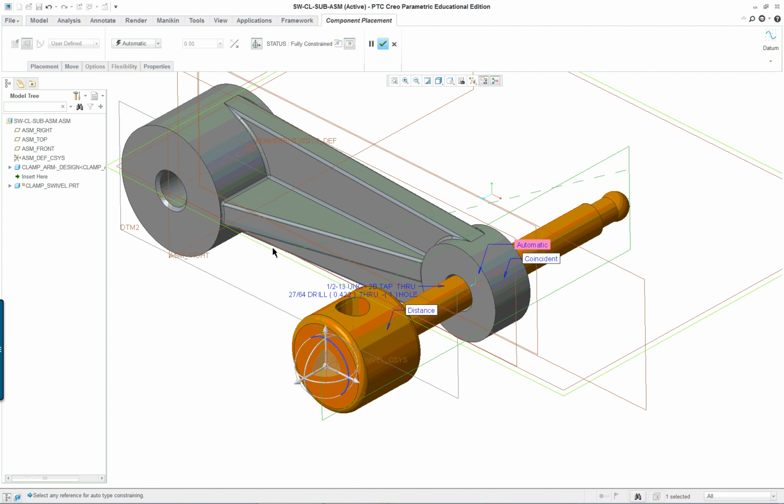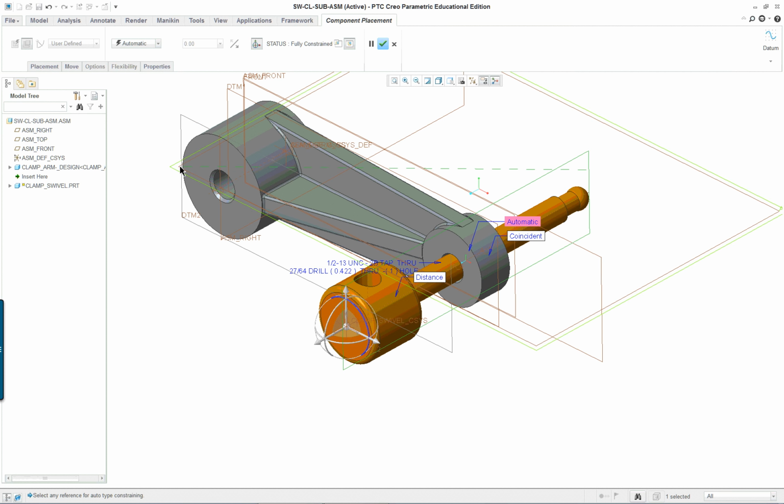And let's select a datum plane that goes down the middle of the assembly, or we can do it in the middle of the component itself also. A little harder to pick up here. I'll just use this datum plane. Use whatever's in the book. Main thing here is we're getting these at 90 degrees. And let's see what we've got.